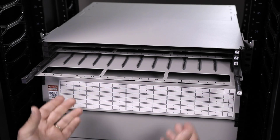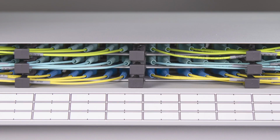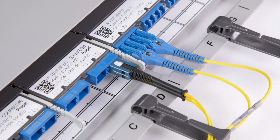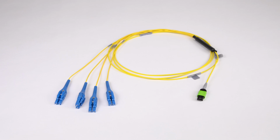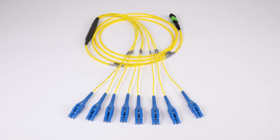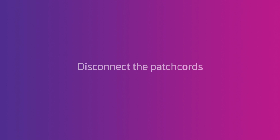Let's say you need to make a configuration change. Maybe you need to add more ports or transition from duplex to parallel to better align with your application. Propel makes it easy and fast. Say you want to keep the same fiber count, but transition LC duplex to an MPO 8, MPO 16, or SN connection on the local network device. Start by disconnecting the patch cords.